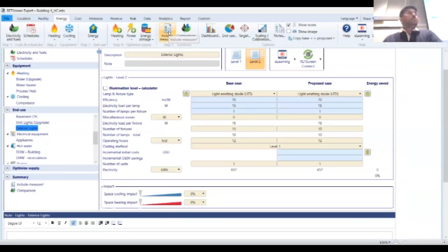All right. So now we have predicted savings, and I want to stress predicted because this is an energy model and we've predicted how much savings we're going to get out of these measures. I know that the measures were roughly implemented in about 2023. I may or may not necessarily have the timeline of the measures. We are, let's say, in '25 now, and I want to see how much energy it actually saved. Can I do an M&V? The answer is yes. We can run a measurement and verification. We can run data analytics and see how much energy we've actually saved.